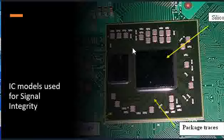In that case, using the model editors, signal integrity engineers generate a model or replicate a model from other manufacturers' IBIS models and try to use it in the simulations. This actually doesn't give too much confidence in the simulation, but there are some assumptions that are definitely required at that point. So that is one more problem which is commonly seen.